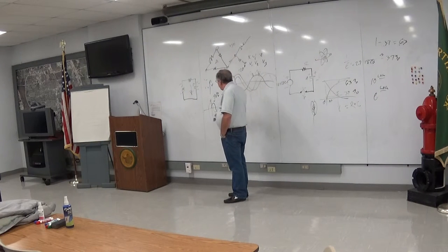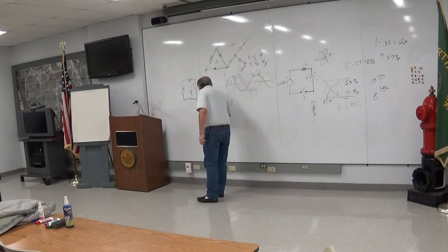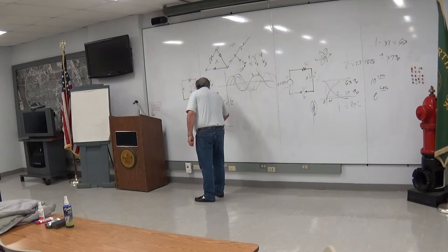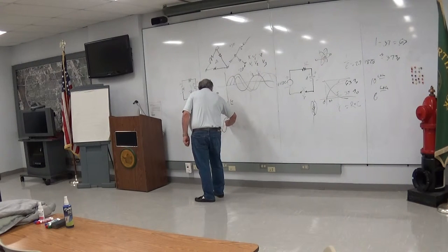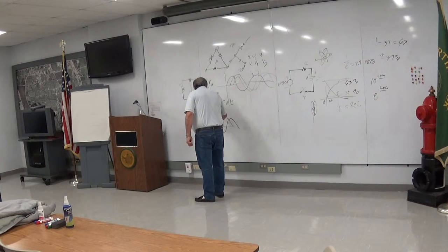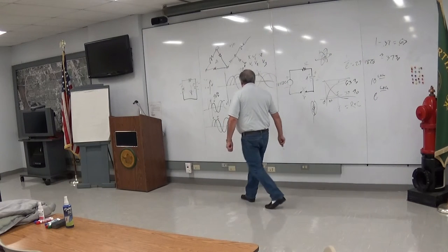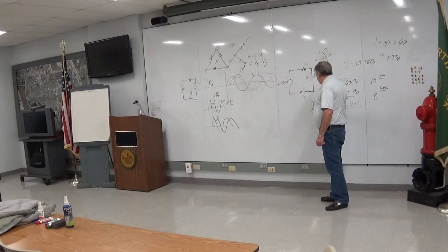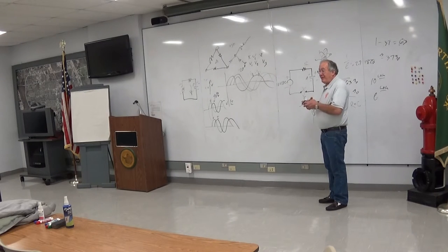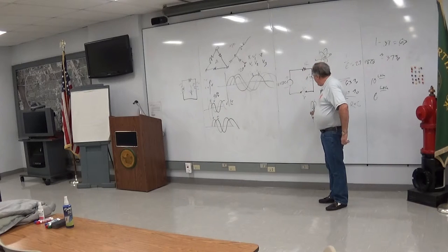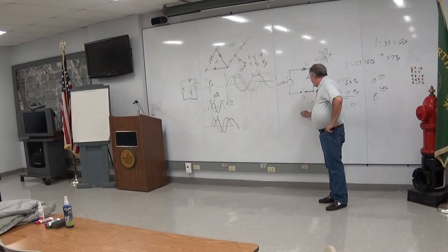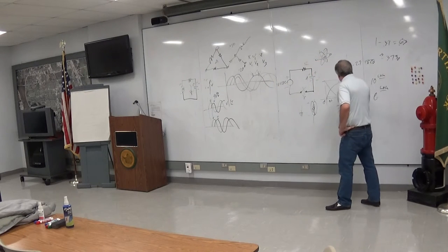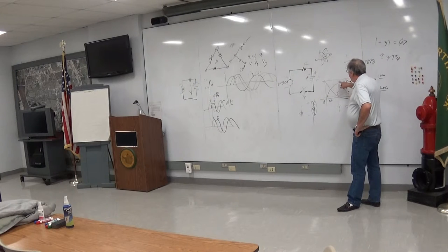Okay, so you have this lag. And by the way, if there's an inductor, it's going to go exactly the same way in reverse, meaning starting 90 degrees late and continuing to be 90 degrees out of phase, you're going to have the voltage first and then the current. Why the voltage first? The switch closes. If it's an inductor, it sees the magnetic field go through, produces the backward EMF, it produces a voltage here, and until that magnetic field collapses, the current is nothing. So the voltage will be the one that's immediate and decays, and the current will be the one that builds up over time.